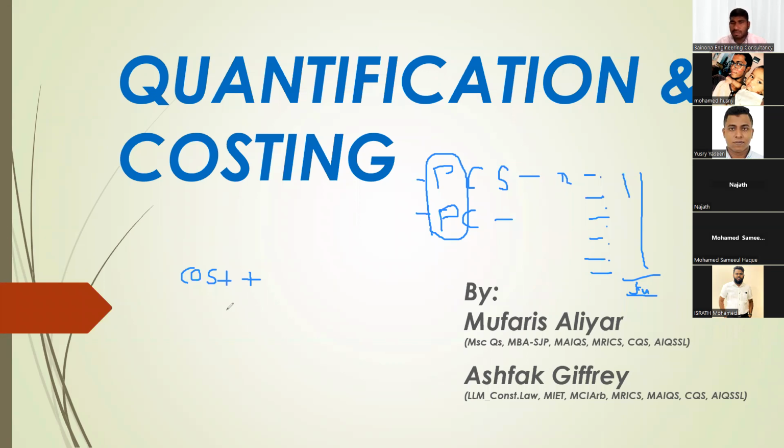What do you mean by lump sum? You agree the sum with the contractor to carry out that particular work. For example, we agreed 1 million with the contractor. The contractor will carry out the work within 1 million. If there is a deviation from the contract, such as specification changes or design changes, only then it will come extra to the contractor as a variation. Otherwise, the agreed amount has to be paid to the contractor. That is the concept of a lump sum contract.